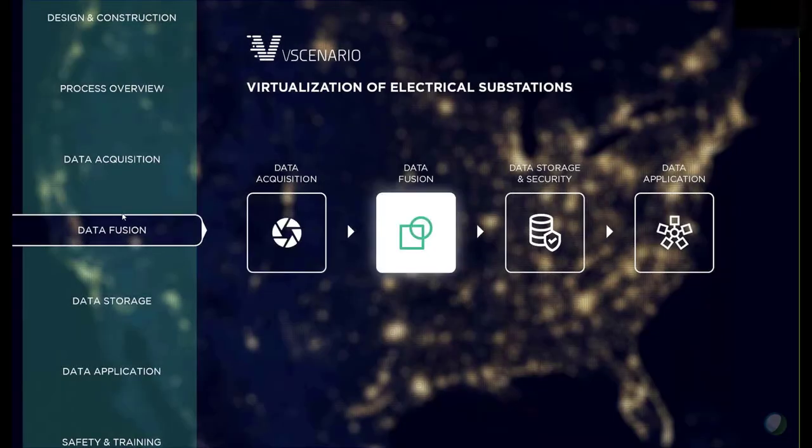And so in order to do that, we need to get everything on one coordinate system. Okay, and so we do that with just traditional surveying. We have a handful of visual ground control points on site. What that allows us to do is map all of these data sets to one singular coordinate system. Okay?